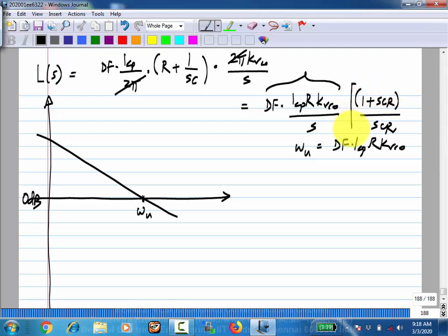And then, what does the Bode plot of this part look like? It will start with a minus 20 dB per decade slope and then become equal to 1, okay? So, it could be like that, or it depends on RC, right? What is this corner? That corner is 1 by RC.